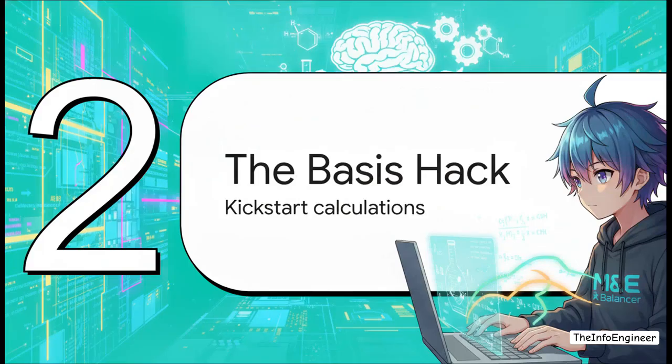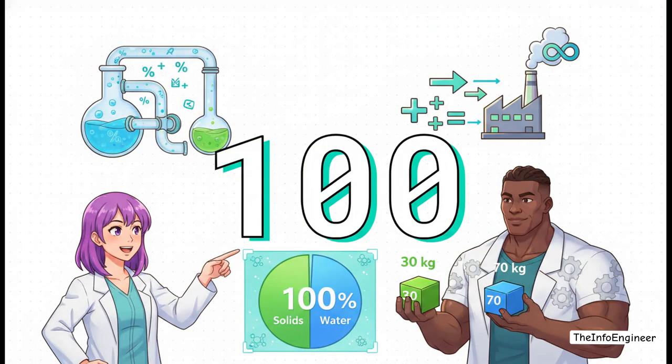Moving on to Section 2, the basis hack. So once we have our boundary, we often look at the paper and wonder, okay, where do I even begin the math? Well, experienced engineers use a brilliant hacker tip for this, the magic number 100. If a problem throws a bunch of percentages or fractions at you, but zero actual flow rates, and you are totally stuck, just assume a basis of calculation of 100. It could be 100 kilograms per hour, 100 moles, whatever fits.